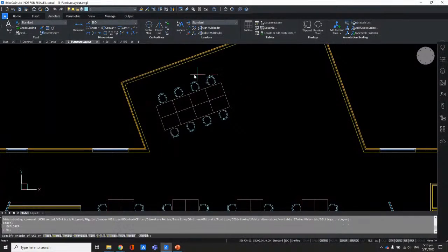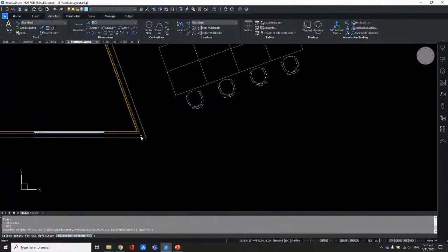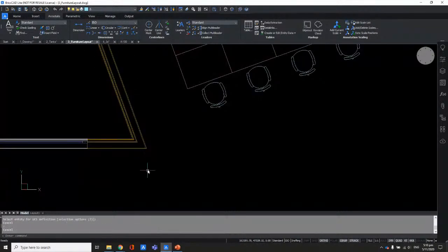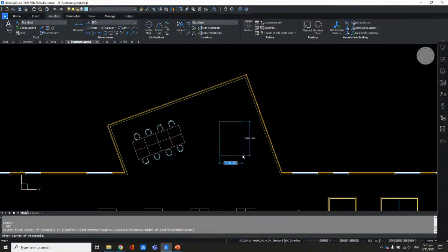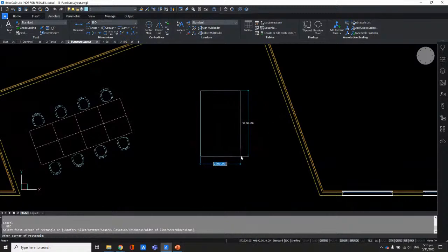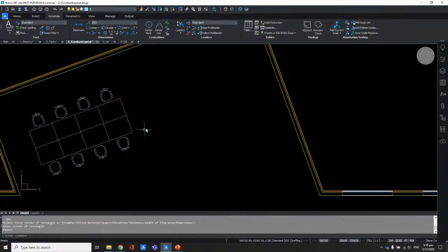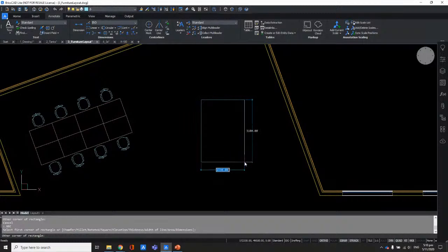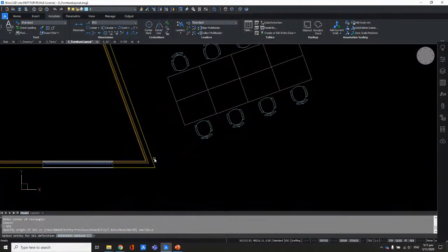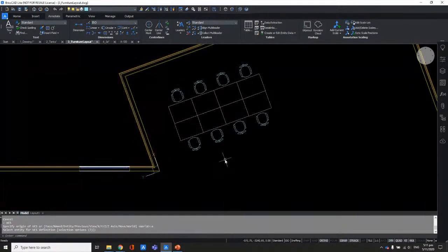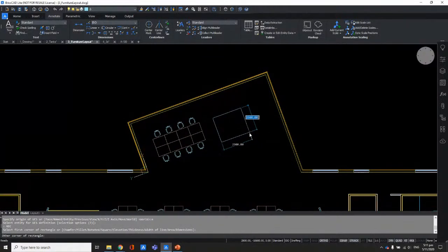And I just want to change my UCS, so pretty easily I am able to change my UCS here. But before that, if you wanted to maybe create a rectangle that represents a table, maybe here, and you wanted it to be on the same angle as these tables here, that's not something easy to do if you are just on this UCS. So you can quickly just use a UCS and entity and just use this. And I can now use my rectangle to create a table here or whatever I wanted to create here.